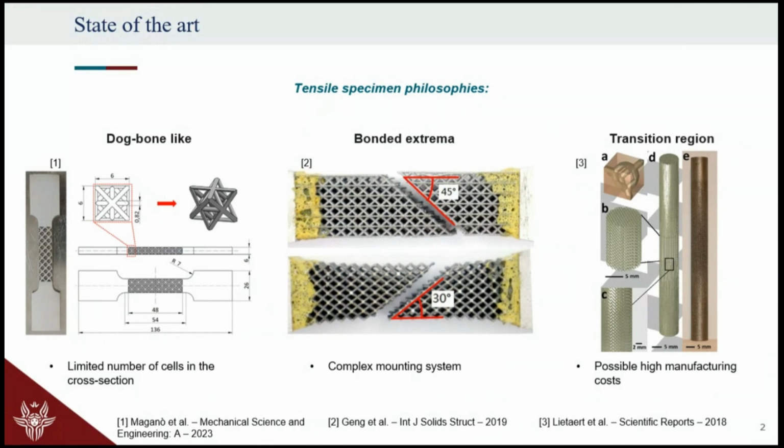It clearly delivers the tensile loading inside the metamaterial, but it is also in contrast with one of the main driving philosophies of the ISO standard, the only one available for lattice structures, the 13314, which considers the need of having at least 10 repetitions of the unit cell inside your specimen. So this is more about testing a structure, maybe, with respect to testing a metamaterial itself.